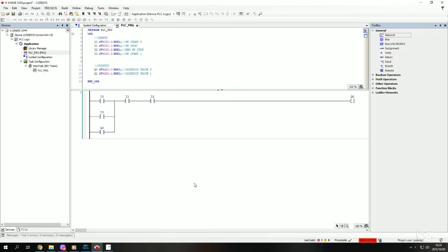Okay, so exercise 4, optimizing the inspection of beverage crates. The statement is too long. I'll only read the description of the process. The cylinder of a piston rod should advance as soon as the push button is activated. After the piston rod reaches the front end position and activates a magnetic proximity sensor, it should be retracted automatically.